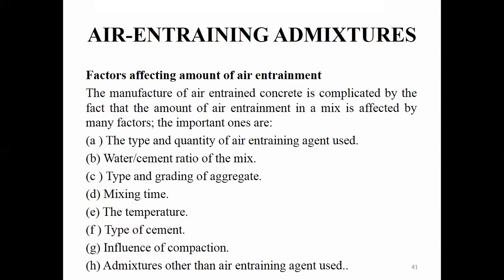Okay. Next, coming to the temperature. Temperature also shows a significant effect on the amount of air entrainment. If the temperature of the concrete, meaning the temperature of the environment, increases, the amount of air entrainment will get reduced. This is also one of the important points.